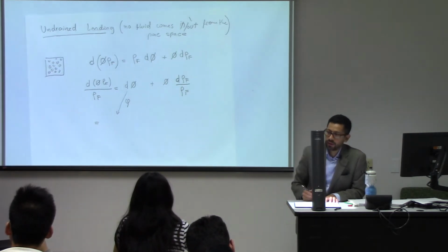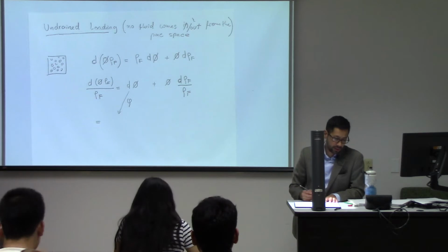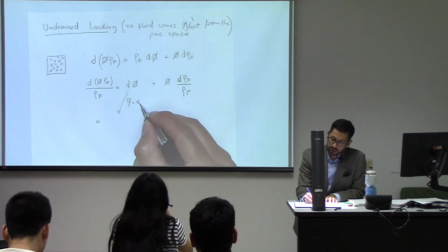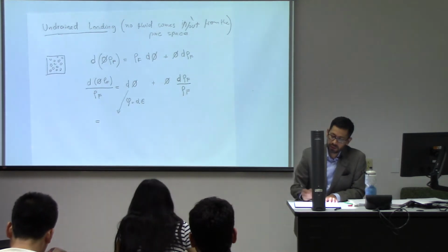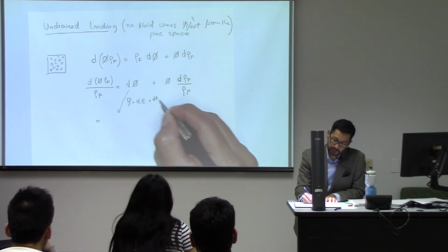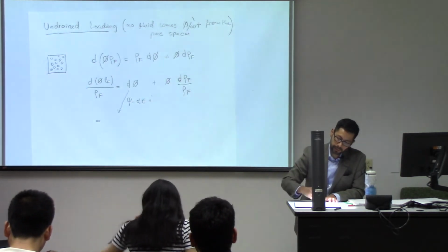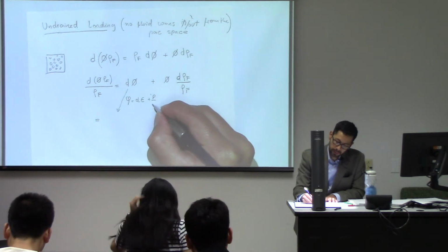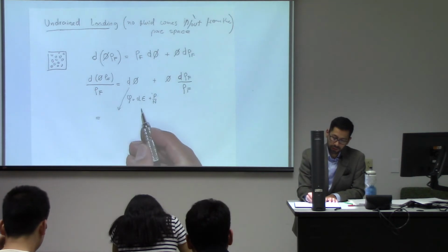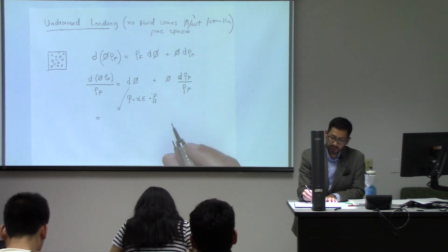We call it this var phi, a Greek letter. And we had an equation for that. From poroelasticity, this was equal to the Biot coefficient times the volumetric bulk strain plus the variation of pressure divided by the pore modulus, right? So if I replace this in here, but notice that again we have a derivative, right?